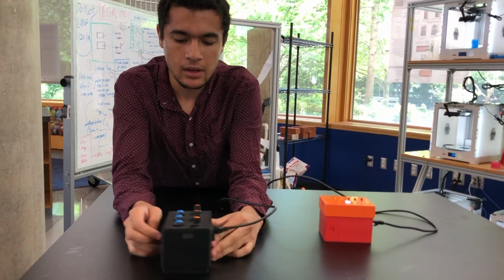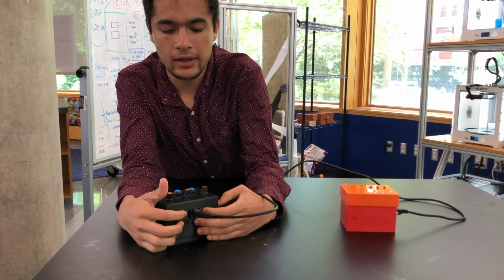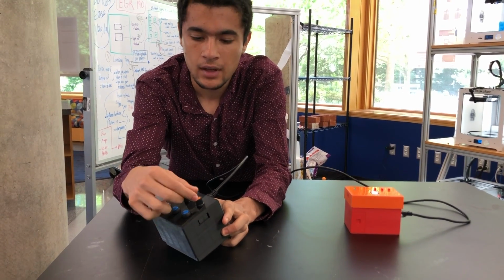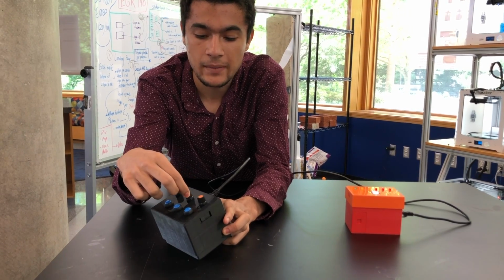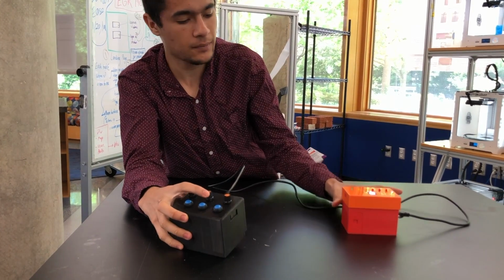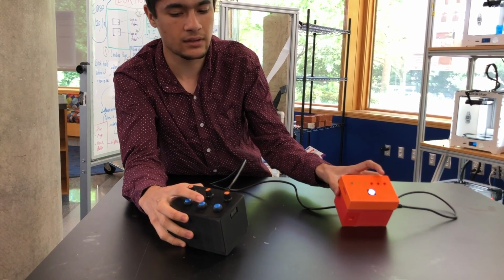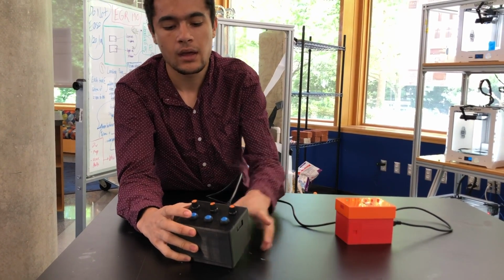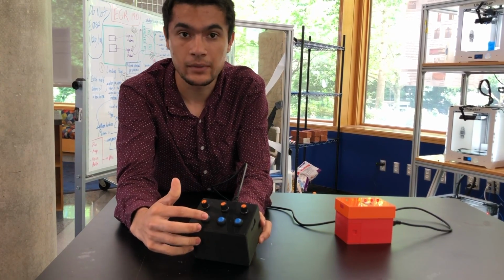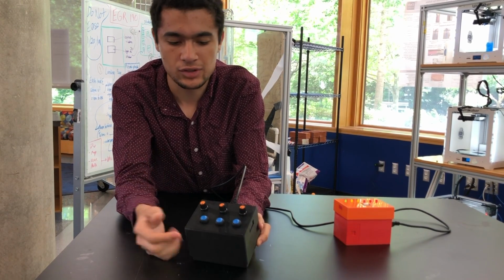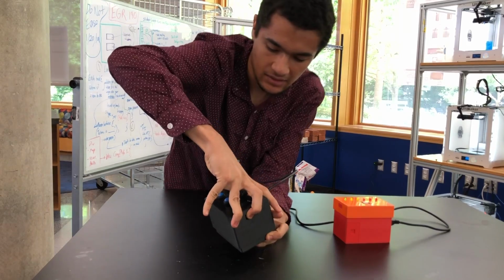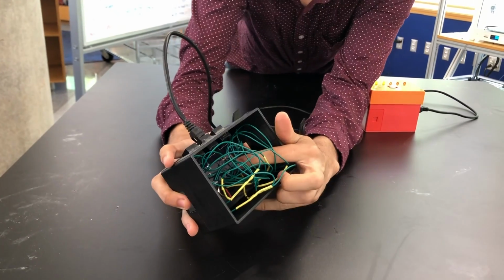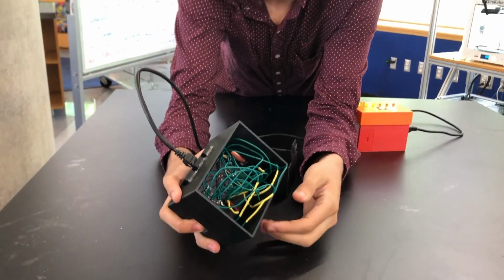As for the teacher box, it contains 3 Ethernet ports for 3 separate boxes. It contains 3 potentiometers, which can be adjusted to change the amount of time it takes for this timer to go. So if we put it all the way to the right, you'll see that the timer is a lot longer than it originally was. And then, of course, these 3 are the reset buttons, which reset each question after it's done. Inside of this teacher box, we see another custom-made PCB, which essentially just makes the wiring a lot easier to be done.